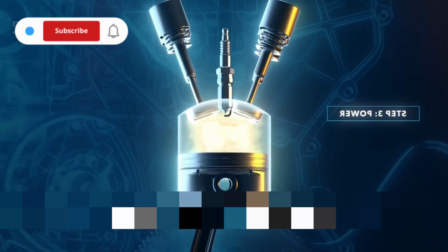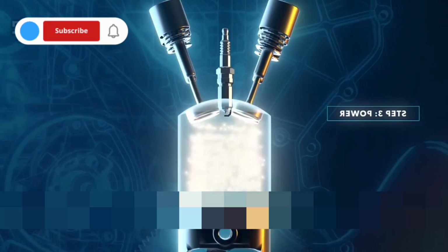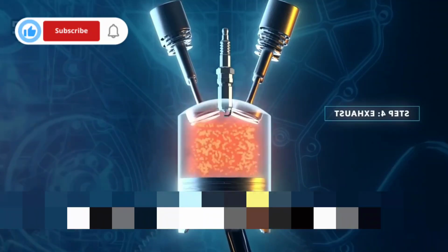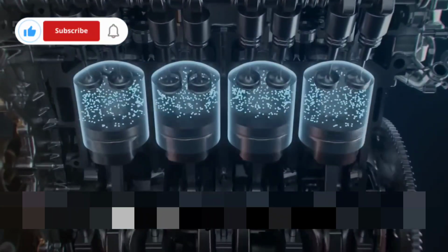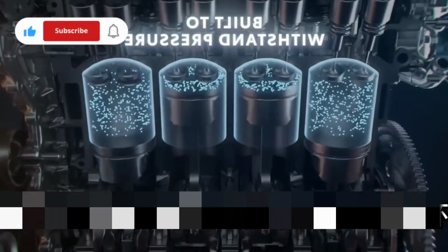The third stroke is power: the spark plug ignites the mixture, and the mixture will deflagrate immediately. The thrust from the deflagration will push the piston down, and the fuel will be converted into mechanical kinetic energy at this time. The fourth stroke is exhaust, expelling the burned mixture out of the cylinder. This cycle is very fast. At 3,000 RPM, a single cylinder of a 4-cylinder engine completes 25 4-stroke cycles per second.